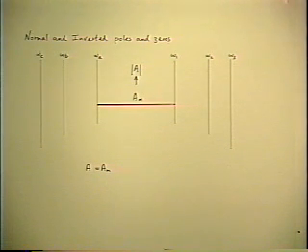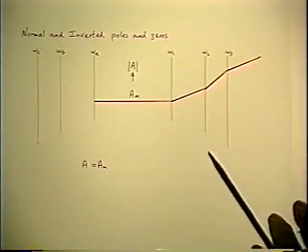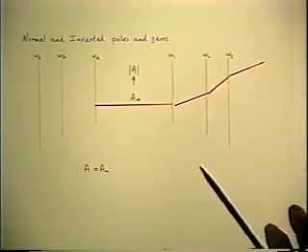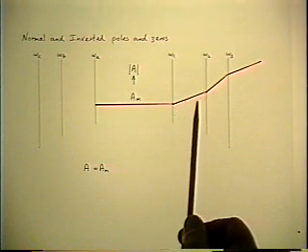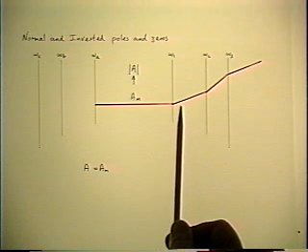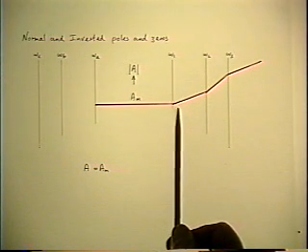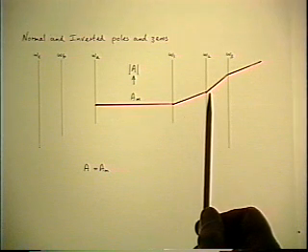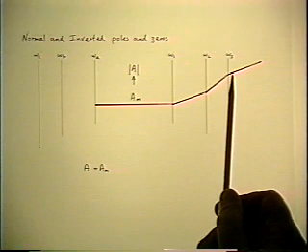But now, suppose we have some higher frequency corners. So suppose at omega 1, the asymptote bends upwards. That's a concave upwards corner. That's a zero. At omega 2, it happens again. So there's another zero at omega 2. At omega 3, it bends the other way.